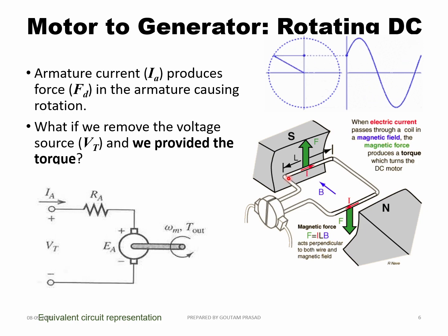So some voltage will be induced on the left side, some voltage will be induced on the right side of this coil, and they will be additive. So the total amount of the voltage induced will be the sum of these two sides' voltages. And if you increase the number of turns, this voltage is going to increase with the increasing number of turns. But let's discuss the shape of the waveform that is getting developed when this coil is being rotated with the help of a prime mover.